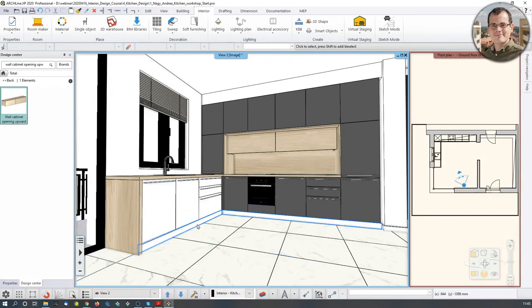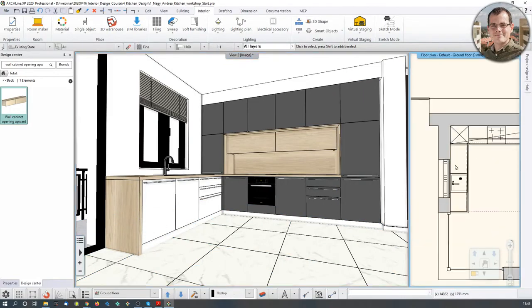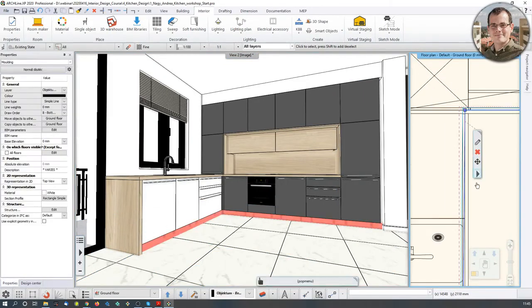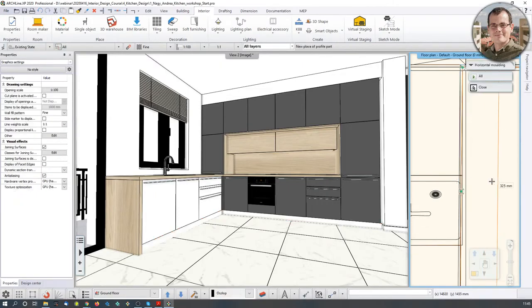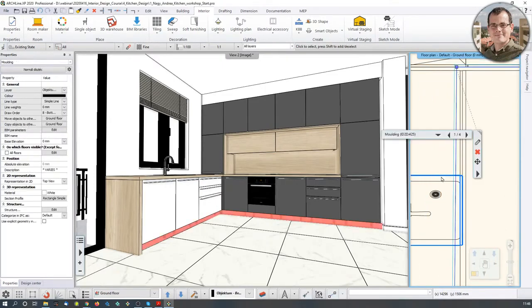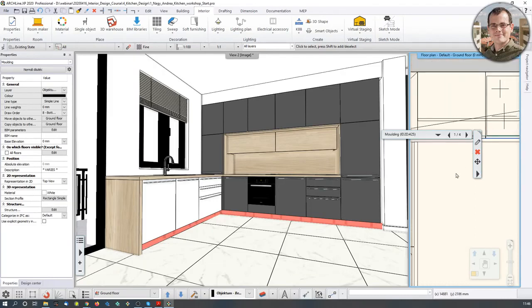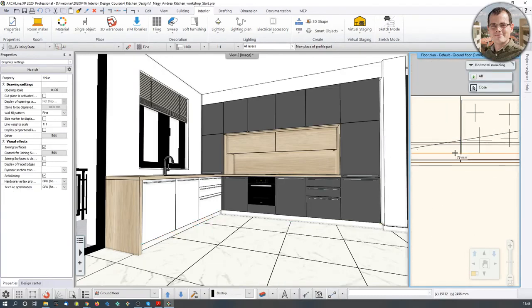One thing you could be customizing if you need it is where this plinth actually is. If you highlight the plinth, which is over here, you can click on the nodes and the sides, and you can offset things back and forth. So if I want to offset it a bit backwards, maybe 50 millimeters, you can do that like that. So you just hit offset and move it backwards.